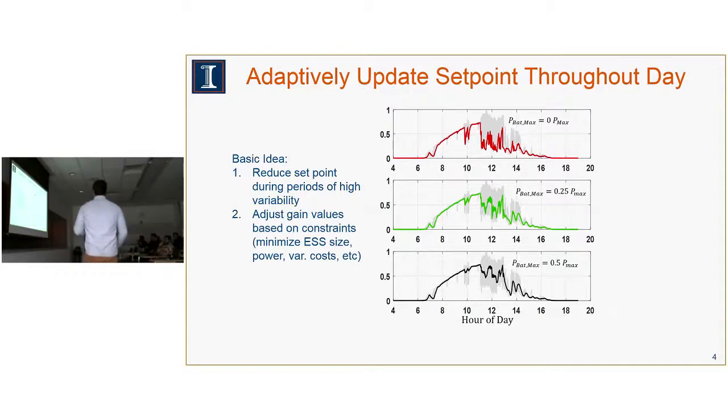And as soon as you do that, if you're trying to optimize a certain variable that isn't just energy production, so if it's energy production plus variability, or energy production plus your storage size, then off maximum power point becomes more optimal than just tracking the sun.